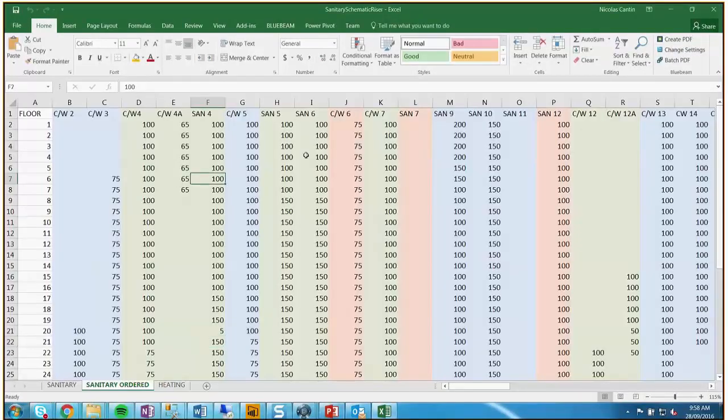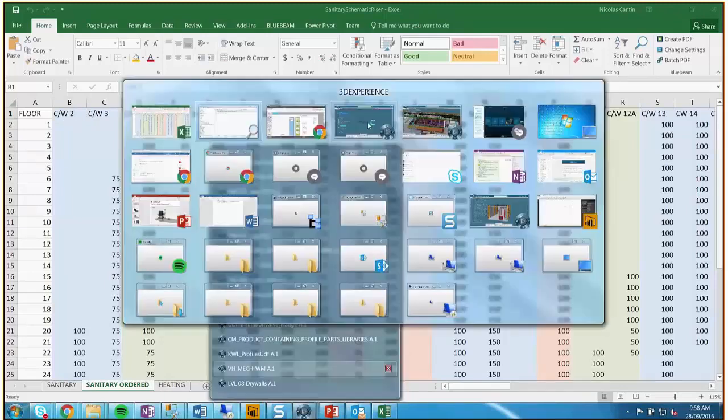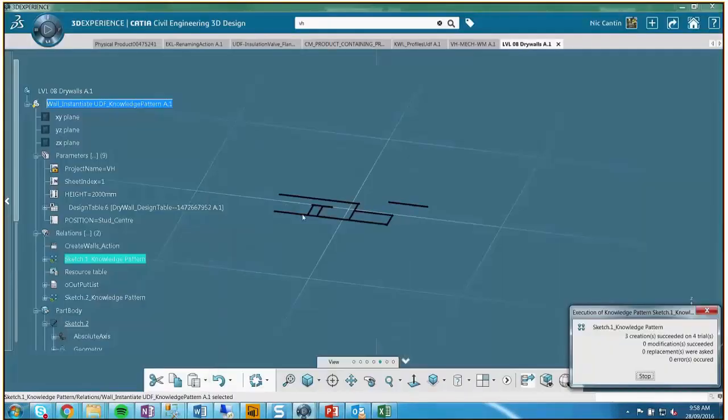Recreate a sanitary riser schematic with all of the sizes associated to each floor. And then based on the sanitary stack number, we can type that as a node, similar to what we're doing with the UDF, the tool for the UDF and the lines. So each of these lines will have a point associated to a sanitary stack, and it'll also have a circle. So when we create this, it's not just a point, sorry, it's actually a circle with a center point.